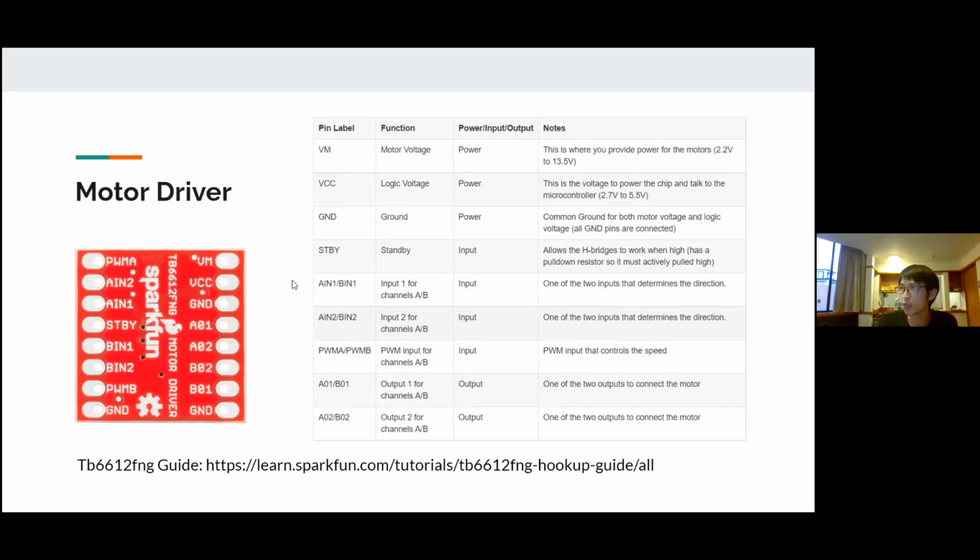Oh, and by the way, speaking of this, because I received some questions on it as well. The battery, you have 2 battery supplies. One of them is the 9-volt battery, and the plan is to connect that to the Arduino, and you got the 6-volt battery and the 6-volt battery case, and that is to power the motor driver.